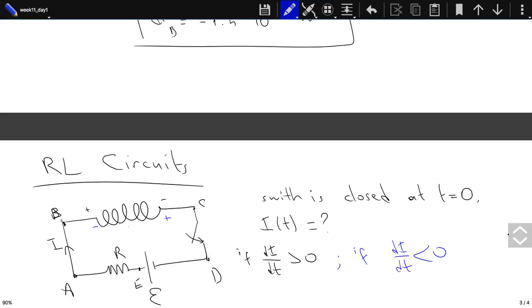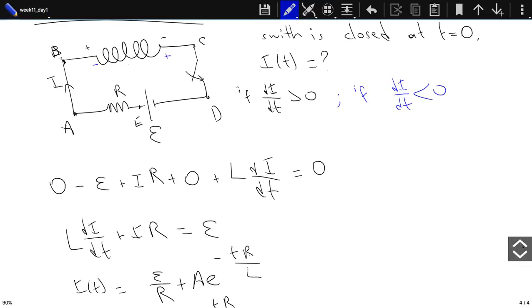On the switch. I mean, you cannot just break the circuit instantaneously. It takes some time. If you try to break it instantaneously, what happens is this di by dt term. You are causing this to be infinite. But if you are causing this to be infinite, you are creating an infinitely large potential across the switch. But that is already large enough to cause an electric breakdown of the air. So there's a slight spark. Yeah, over there also. Which is not a nice sight.